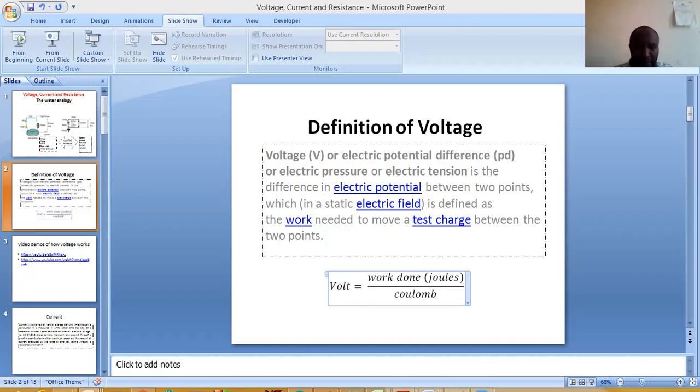All these expressions are true when you are computing voltage, and using the definition of electrical power and Ohm's law, you can very easily show that this is the case. Same case for resistance. All these expressions in this portion of the pie chart give expressions for computing resistance of a circuit.